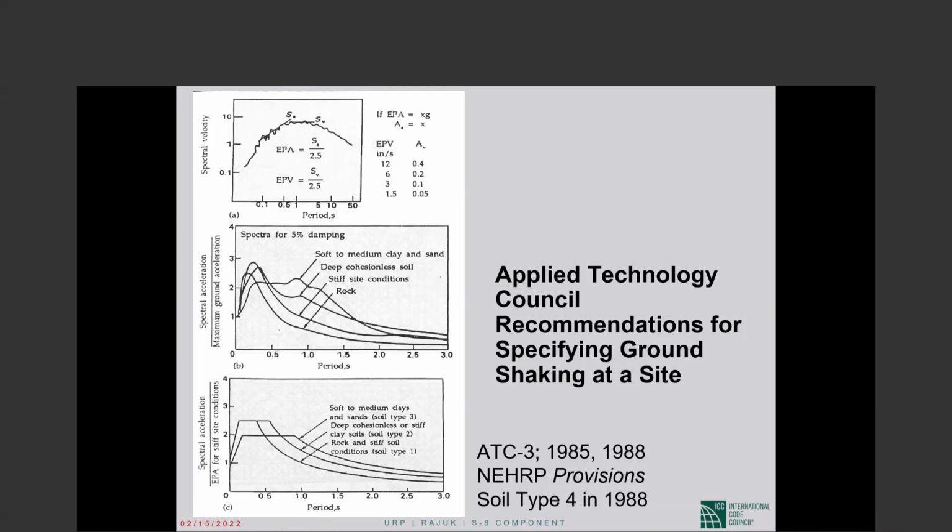So these spectra, acceleration on the y-axis, because spectral acceleration, remember, is directly related to base shear, was adapted for building code use in the very important ATC3 document that I am sure I mentioned. ATC3, dated 1978, is pretty much the source of the modern seismic design we are doing today.